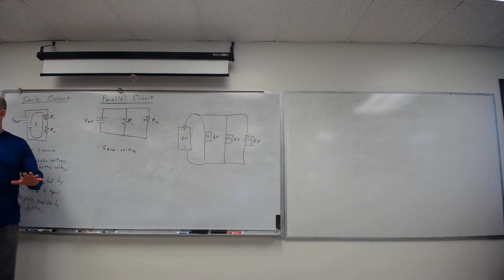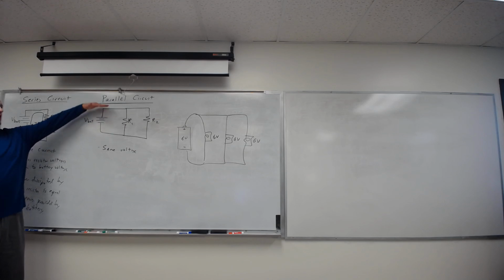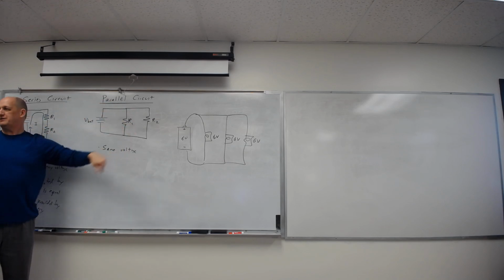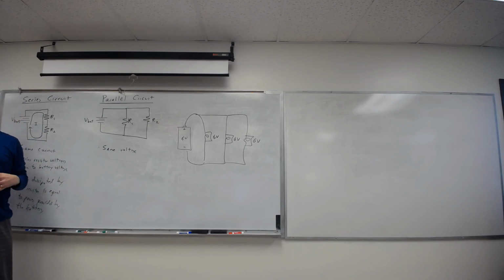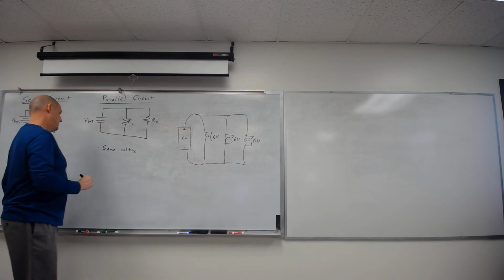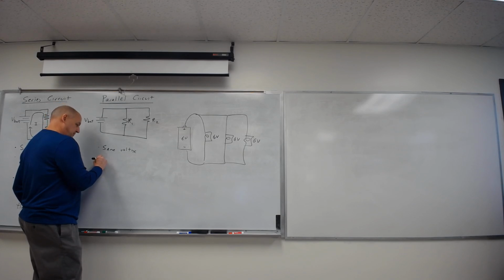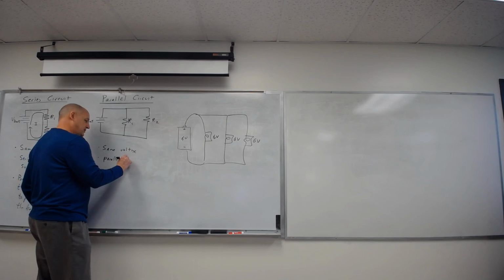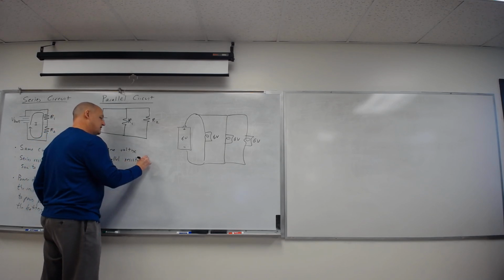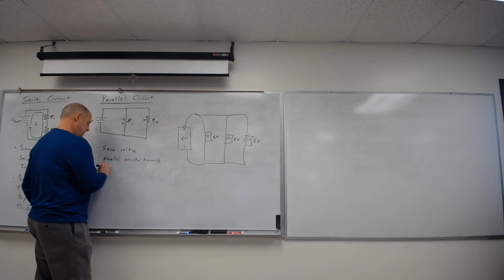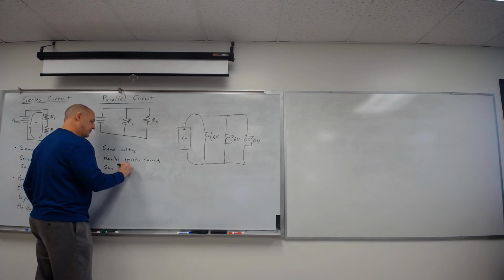Remember my picture of this is the ground, and I go up to a higher level, that's my voltage. These are all the same level, it's just like I have parallel stairs to come back down, or parallel paths to get back down. Here I have one path where I have to go down one and go down the other end and back. Parallel resistor currents sum to the battery current.